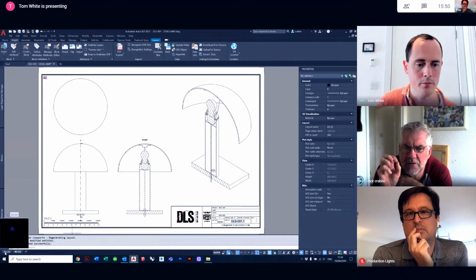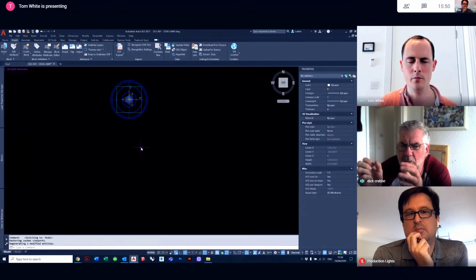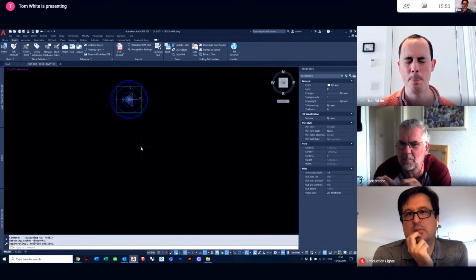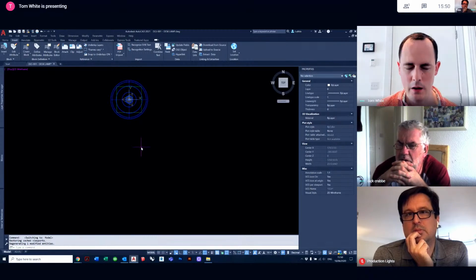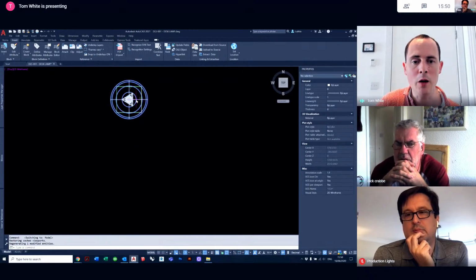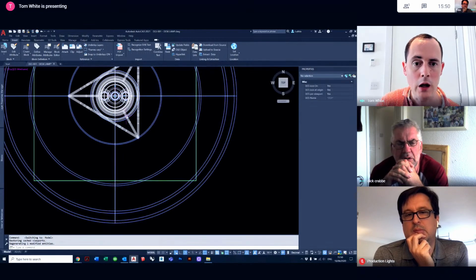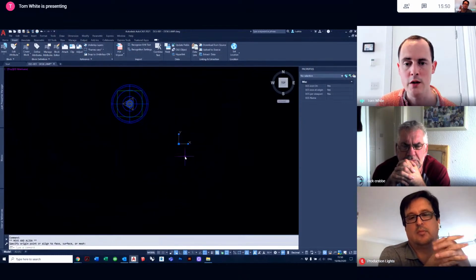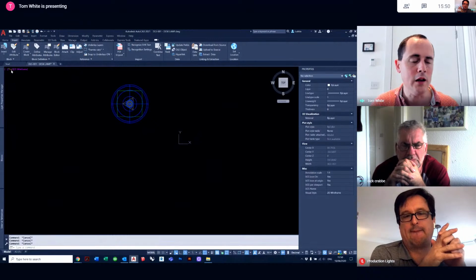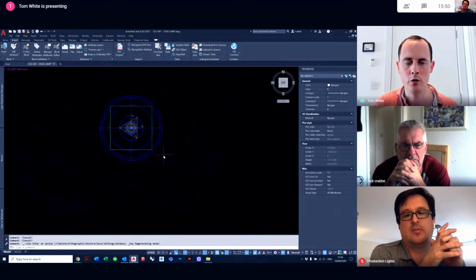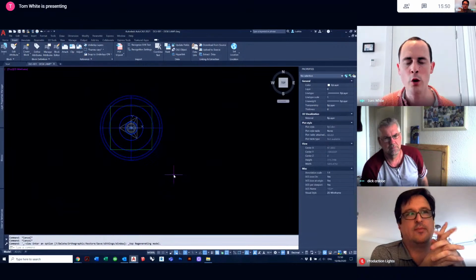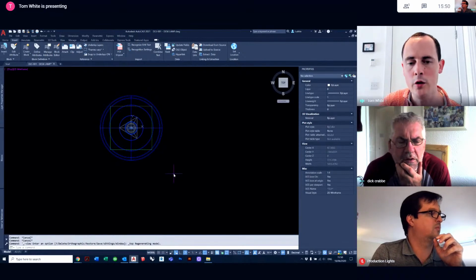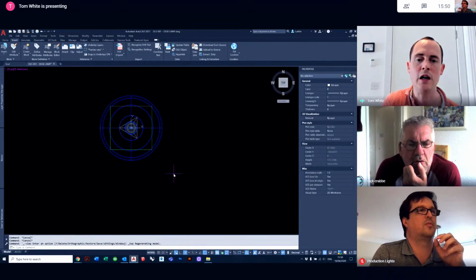So when you went back to world, that resets everything, resets the 0,0,0 origin back to where it should be? That's correct. So I believe the terminology, if you agree, Dom, is that this is a user coordinate system, and I'm going to click on top, and that is a world coordinate system. So the world is always in the same location, but at a glance, it might not necessarily be the case. But the world is one fixed location.